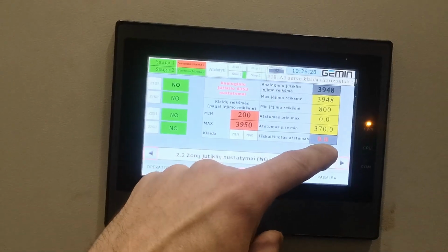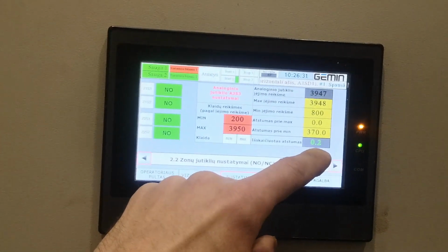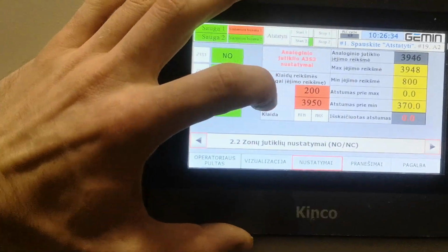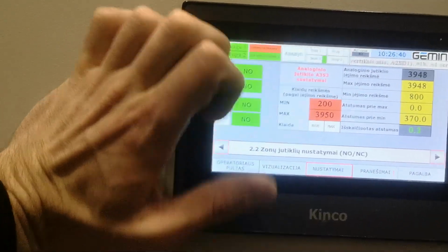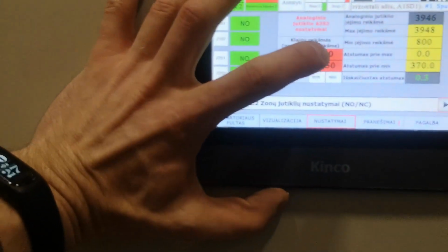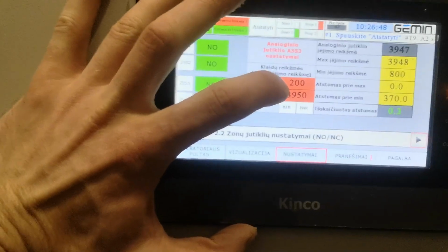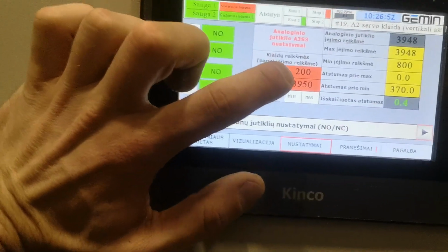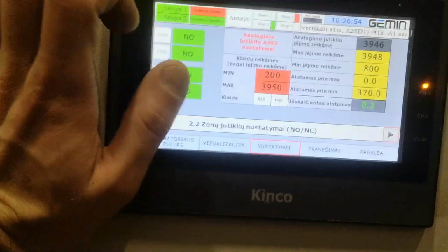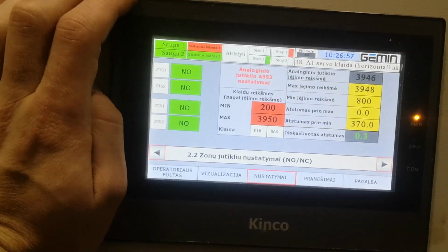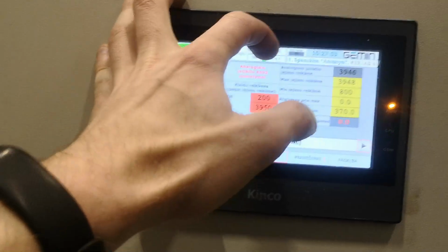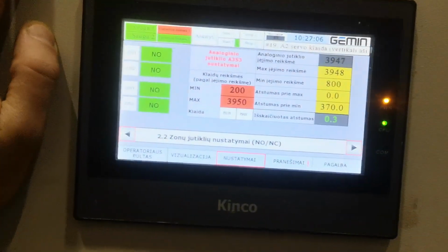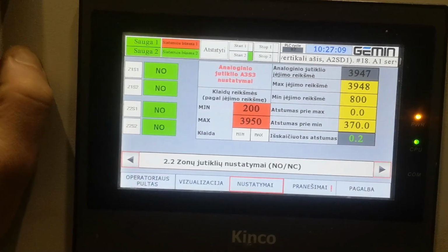And this is the calculated result. And although I have these 2 seconds, when it's out of range, let's say, I have an error. So if I disconnect the sensor, it will be 0, approximately 0, maybe -1, maybe plus 1. So I have used 200 like a minimum, because really my minimum input value is 800, and although I have maximum input value, when it's out of range it displays the maximum.